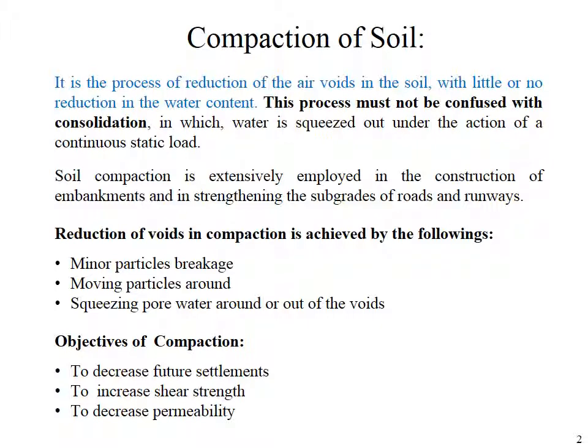Compaction of soil. It is the process of reduction of the air voids in the soil with little or no reduction in the water content. This process must not be confused with consolidation, in which water is squeezed out under the action of a continuous static load. Soil compaction is extensively employed in the construction of embankments and in strengthening the subgrades of roads and runways. Reduction of voids in compaction is achieved by the following: minor particles breakage, moving particles around, and squeezing pore water around or out of the voids.